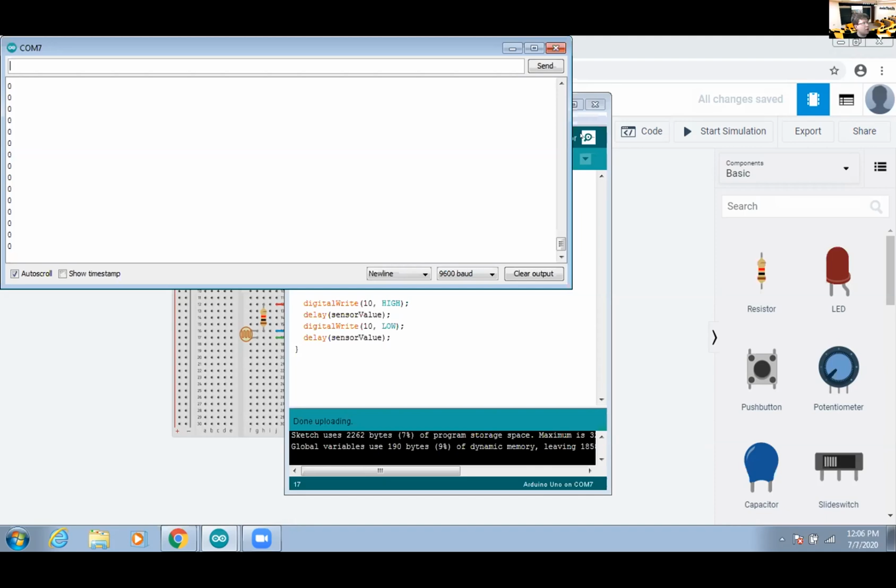So basically right now your sensor value is showing 0. That means that your delay is 0, meaning that there is no delay and it's always between on and off. So it will be glowing with half capacity. It's not full brightness, but it's not completely off either. Now we need to make sure that your sensor value is adjustable within a reasonable range. So find the resistor from the pack that says 1K and put it in the position that is next to the photoresistor.